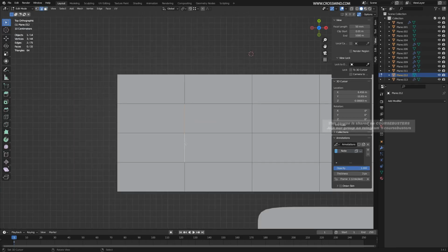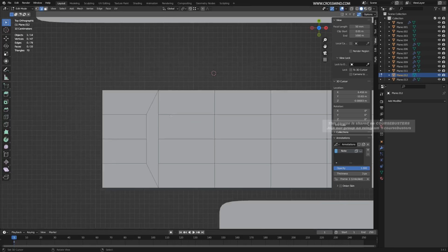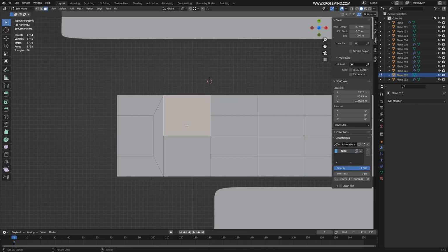You can also do the same thing by ripping these apart. Select two of these, press V and rip this apart. And now you can simply fill this area and then you can dissolve these two edges. There you have a quad here, and these are also quads.